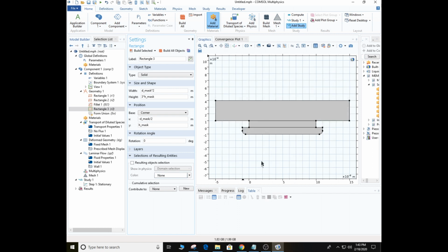For this right here, our chemical species is coming in this way and flowing right across. Some of it is going to come down here and interact with this surface and start etching it away. This part right here is not going to get etched away because this chemical species only reacts with this kind of surface, and this is the mask over that surface to protect it. But it's going to etch all under here, down here faster, and under here too. Okay, that's all the geometry.